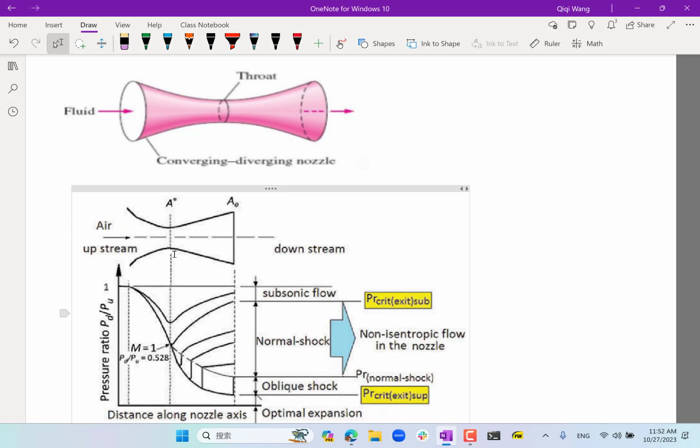At the end of the nozzle, you imagine you have a knob that controls the static pressure up and down. When you have the static pressure almost equal to the stagnation pressure upstream, what you have is pretty much incompressible flow, as we have talked earlier. Incompressible flow means the change of pressure due to aerodynamics is small compared to the pressure itself. So for incompressible flow, you have Bernoulli's. In the throat of the nozzle, you have the minimum pressure, and downstream it rises. Basically, the pressure is going to be monotonic with respect to the area of the nozzle.